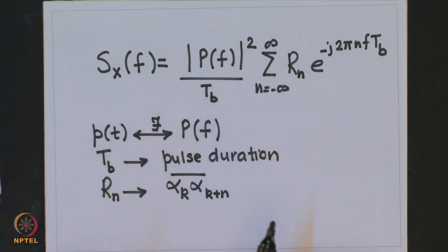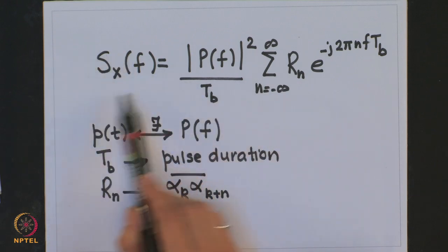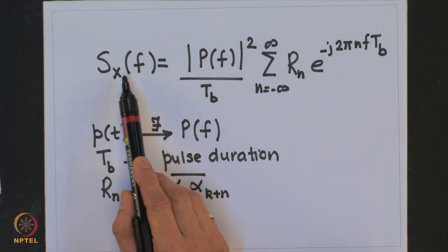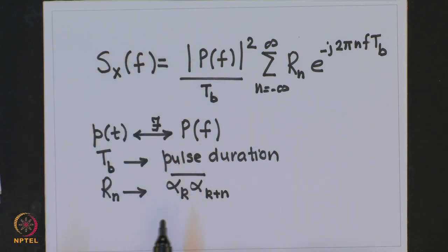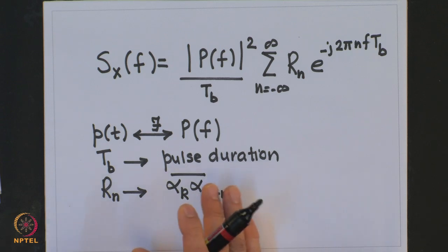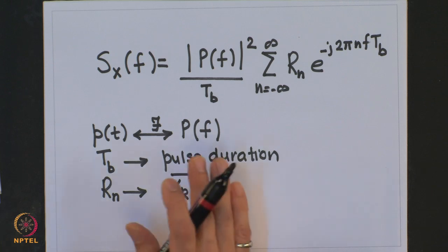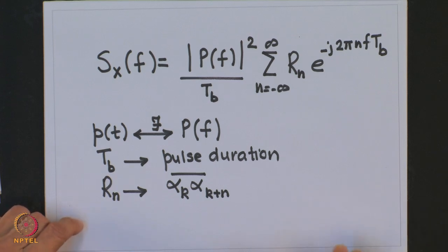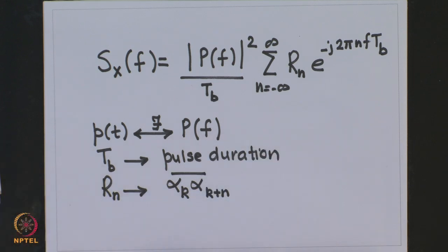We have seen that this power spectral density theoretically extends right up to infinity. So, the theoretical bandwidth of a line code is going to be infinity, and usually these signals are transmitted on a band limited channel. Now, because of the band limited channel, spectral distortion occurs and this tends to spread the pulse. This is also known as dispersion.